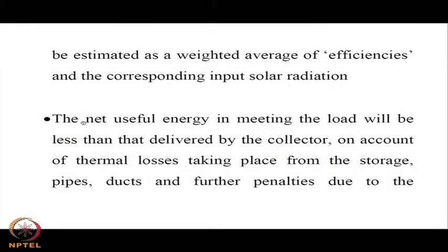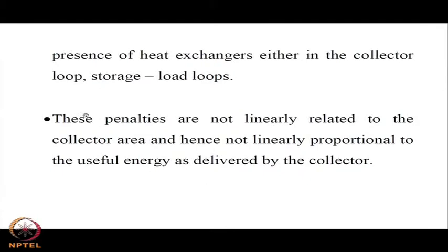The net useful energy in meeting the load will be less than that delivered by the collector on account of thermal losses taking place from the storage, pipes, ducts and further penalties due to the presence of heat exchangers either in the collector, loop, storage or load loops.